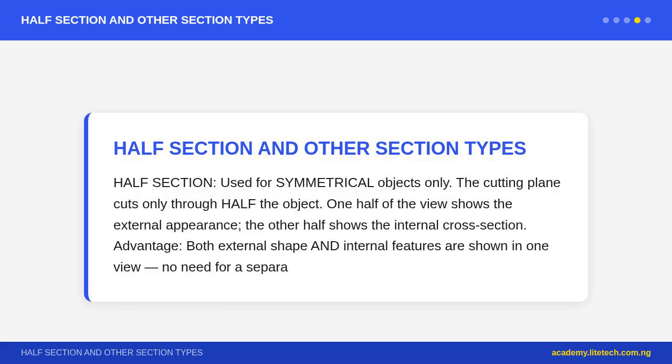Question 2. Describe the hatching convention for sectional views. Answer. The cut surface is hatched with thin parallel lines drawn at 45 degrees to the main outline, evenly spaced, typically 3 to 5 mm. Hatching should not be drawn through holes or hollow areas. Adjacent components in an assembly section are hatched at different angles, e.g. 45 degrees and 135 degrees, or different spacing to distinguish them. Very thin parts are shown solid black rather than hatched.